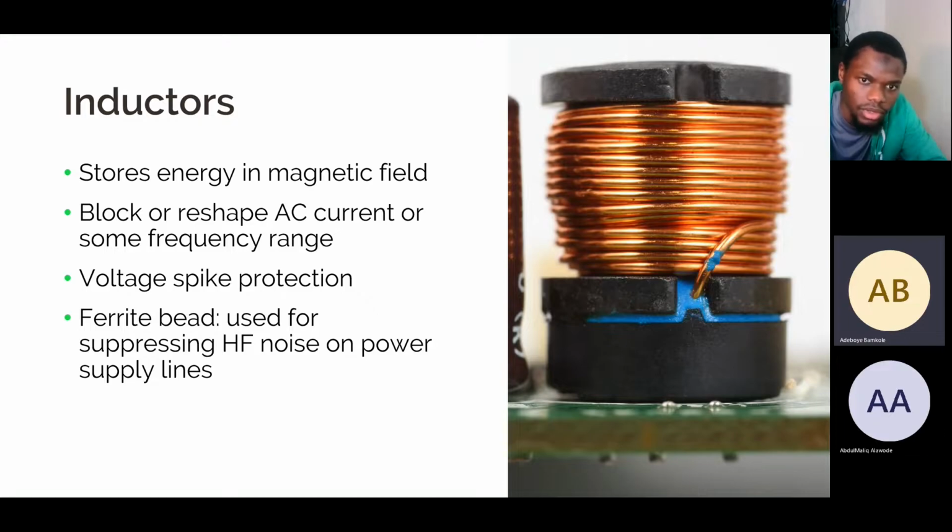Also inductors. Inductors store energy in a magnetic field, they block AC currents, and they are sometimes used as filters. There's a specific type of inductor called a ferrite bead, which is used for suppressing high frequency noise on power supply lines. I'll show you some circuits that use this, and it's also used for protecting against voltage spikes. So that's the basics of these components that you use in almost every design you do. You use capacitors, resistors, and inductors, but inductors are not usually common, but it's good to know about them in case you have an application that needs one.